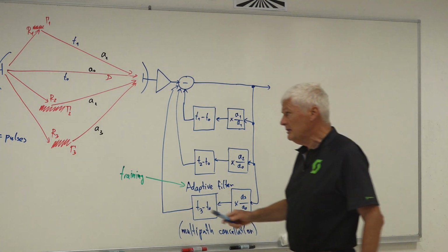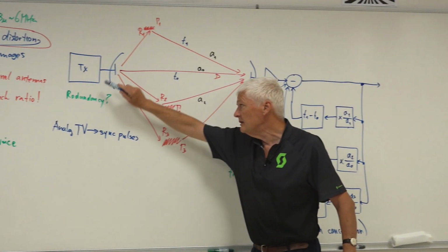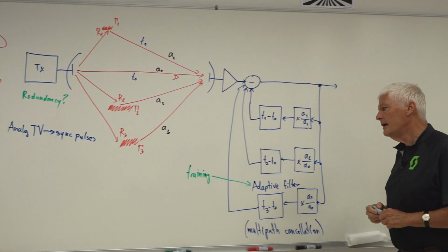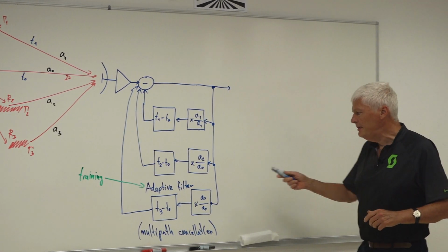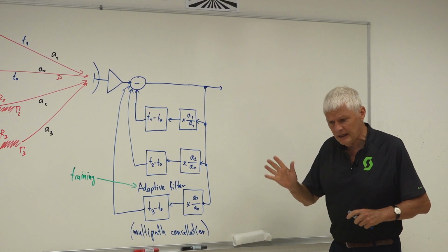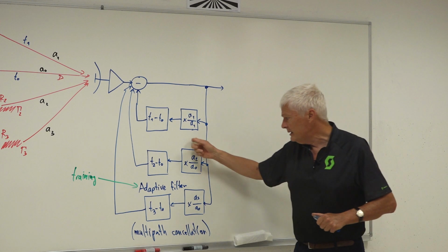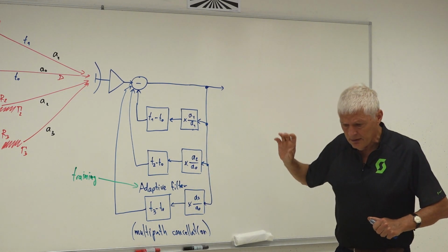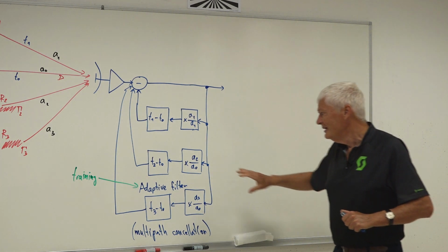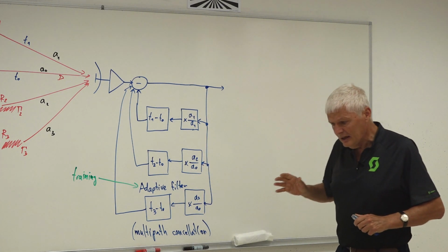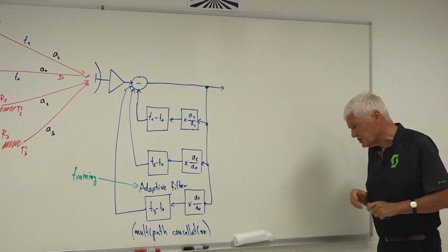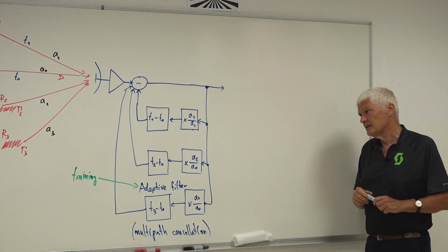Also, the sync signal was the most powerful signal in an analog television transmission. And such a filter could be built. It was quite close to implementation. Some companies like Philips were already thinking about making television receivers that have such filters inside, but then digital TV came out. So this was not used, but it was already developed in the labs, say of Philips and other large manufacturers.